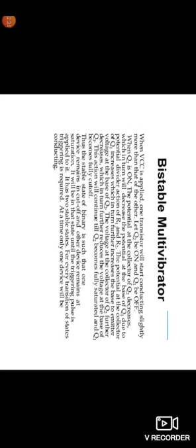And thus the stable state of the binary is such that one device remains in cutoff and the other device remains at saturation. Here one device is fully in saturation, and the other device is in the cutoff state only. It will remain in that state until a triggering pulse is applied to it. It has two stable states. For every transition of state, triggering is required.